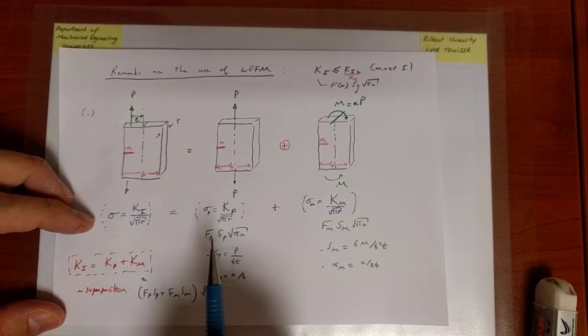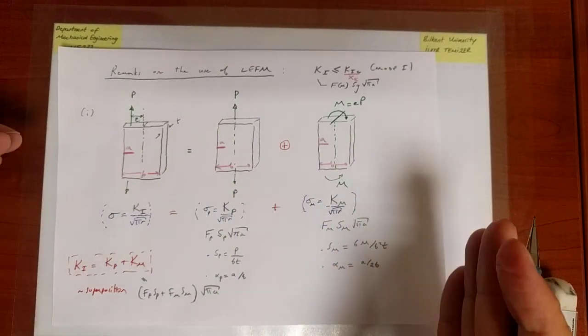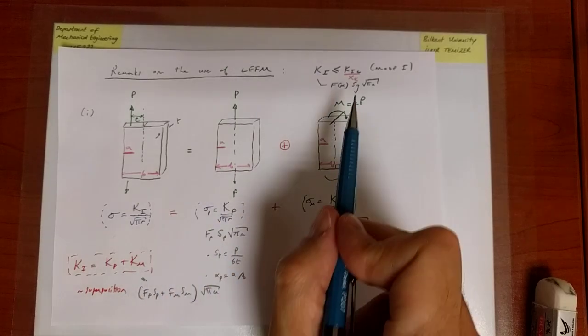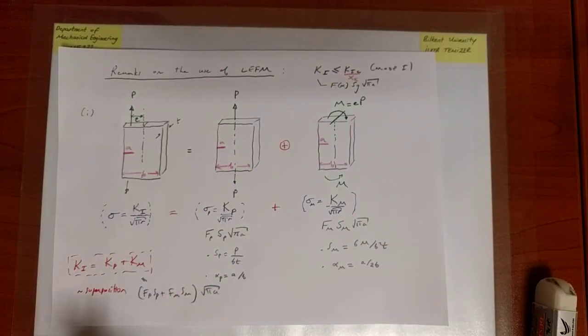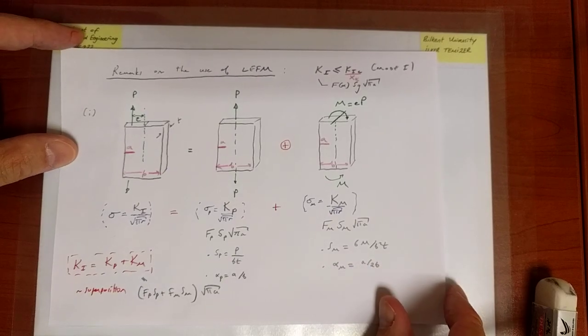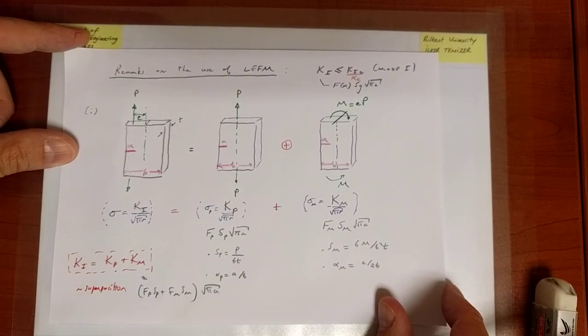What we have to remember is the principle of superposition. You individually attack the problems, sum them, and then assess the criticality of the overall situation through still the same criterion. Okay, so that's the first remark that we would like to address, and this simple superposition criterion allows us to rapidly propagate beyond simple loadings that we have considered and look at really more complicated loadings, examples to which you can find in the book. Now, in the book, you can also find examples to many different types of geometries and many different types of loadings, as I said.